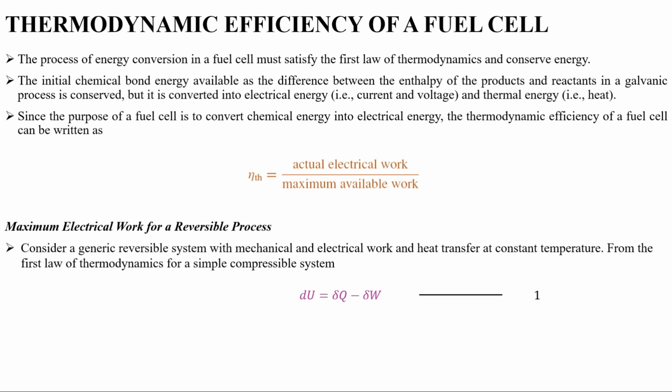They are not thermodynamic properties, whereas U is the internal energy and it is a thermodynamic property. With a thermodynamic property we can use a differential, but with a path function we use δ. So this is the simple first law of thermodynamics: dU = δQ − δW.